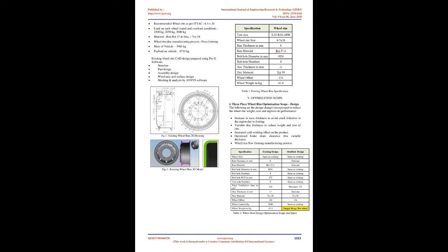2. Problem statement. Currently the TATA 1109 ILCV vehicle's recommended wheel rim size has higher weight and cost, which need to be analyzed and optimized under finite element analysis. Analysis of the wheel rim to determine the material removal area, changes in von Mises stresses and deformation for the current and modified rim design within given boundary conditions, to gain significant advantages for lighter mass vehicle wheels.